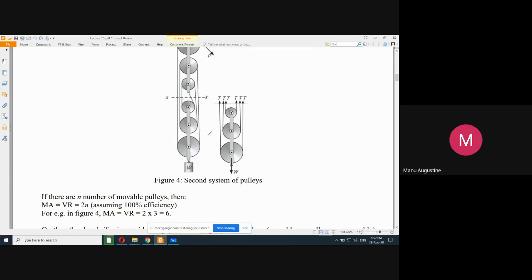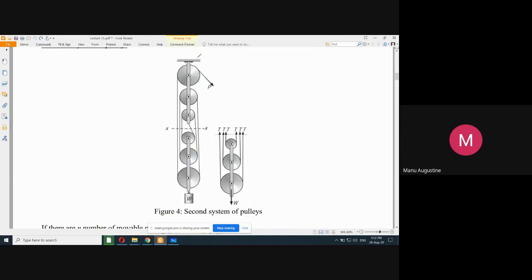अब इसको कैसे बांधा हुआ है धागे से, ये देखो. All the pulleys are connected with one single thread. अब देखो कैसे किया है, धागा यहां से लिया, इस पुल्ली के ऊपर से लेते हुए गए, brought it all the way down to the last pulley, again wound it up, took to the second pulley of the first set, brought it down, took to the second pulley of the second set, brought it up, took to the third pulley of the first set, brought it down, wound it from the bottom part of the first pulley of the second set and then attached it here. यहां पर ला करके इस स्टेम से बांध.